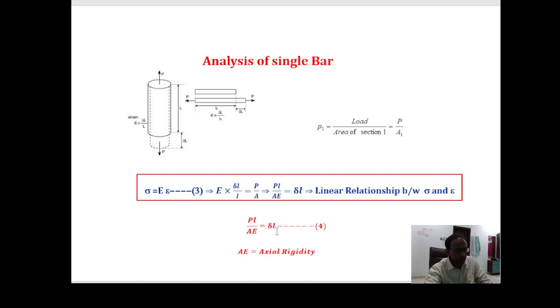Most of the time, when we are dealing with problems, this formulation is very useful, because in practical problems you will mostly know the deformations, which can be measured with deflectometers, or dial gauges.